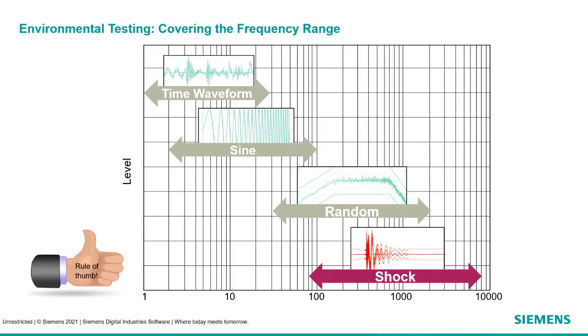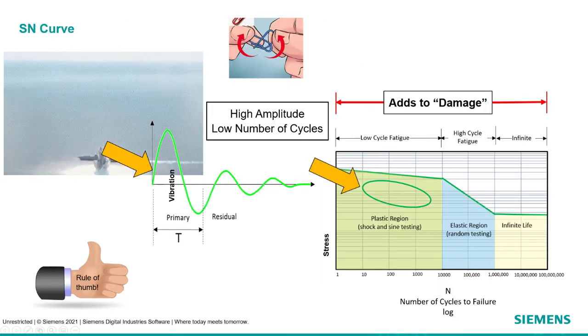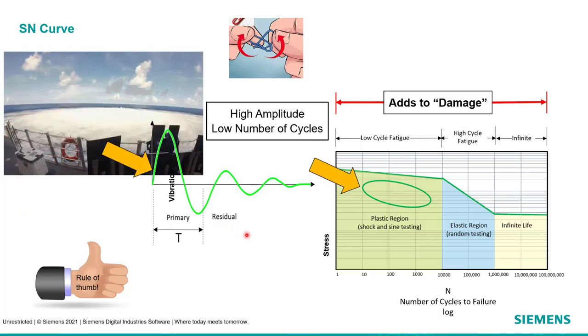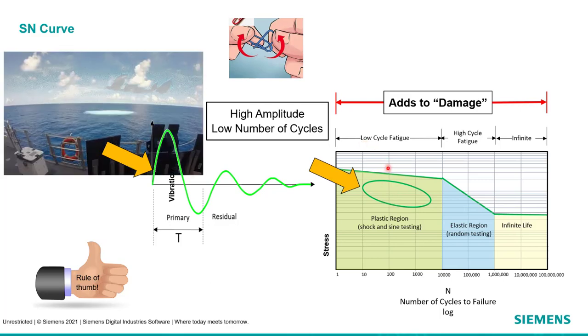So now we move into shock control testing, and for shock control, the rule of thumb as far as frequency content, we'll say from maybe 80 hertz up to 10 kilohertz or so. That's about the frequency range that's applicable for shock events. And this is a video of one of these shock events and one of the applications where shock control would be applicable, for any electronic components or some shipboard components that might be mounted. You would want to expose those with the shock control.